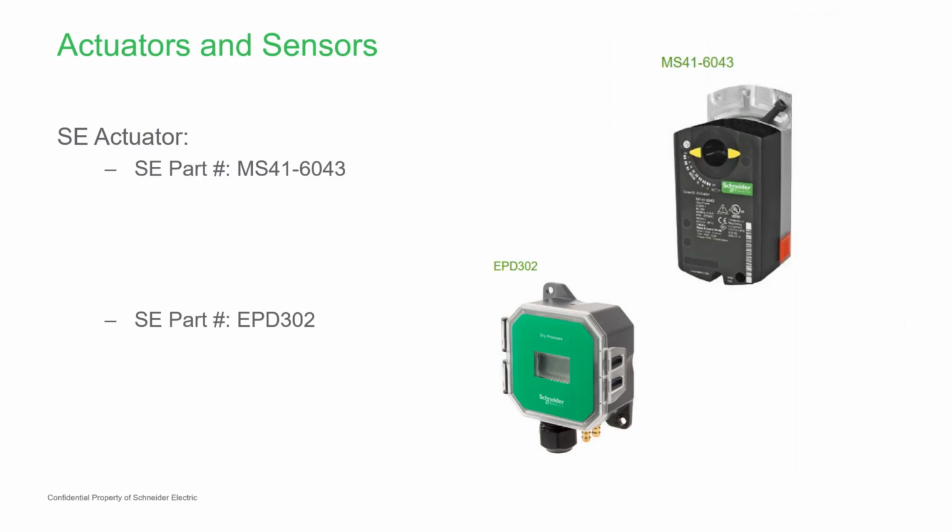So one of the last slides here to talk about this product is the different devices that you would connect to that. Right? We've already gone through the Zigbee stuff, but these two devices here are the things that you absolutely need to work on a VAV box. So the 8250 is the actual controller itself with the I/O built into it. These are examples of a pressure transducer, and a damper actuator that you would need to put on a box.